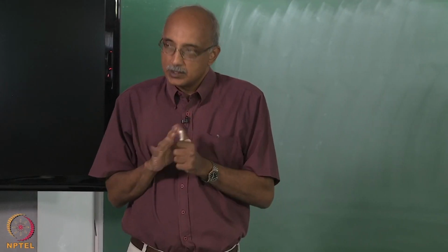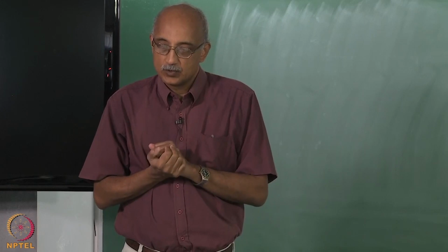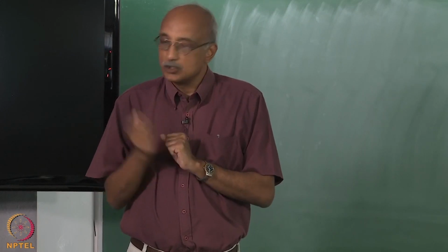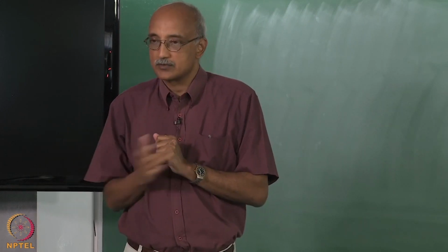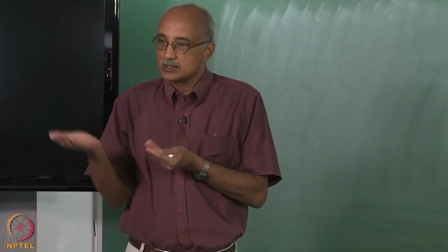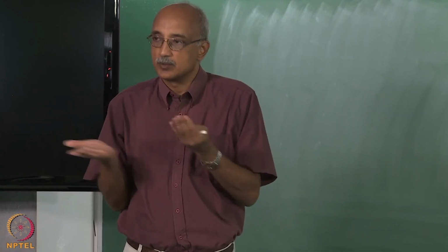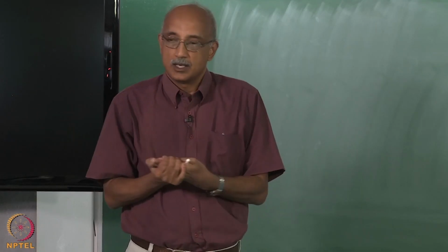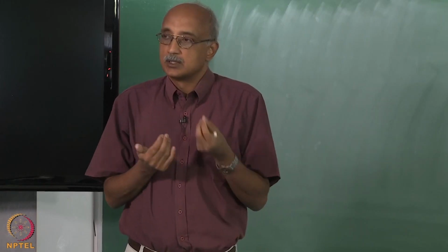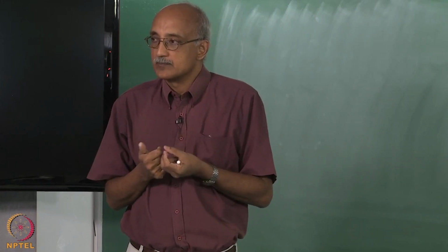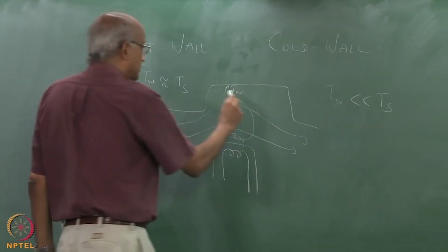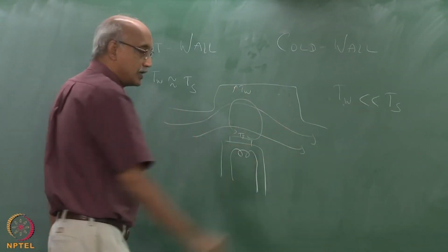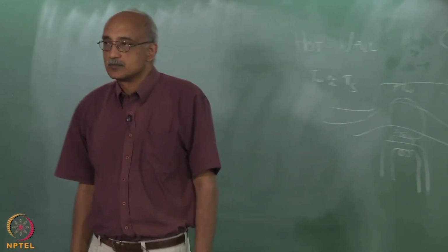The main reason you want a cold wall reactor is so that you make sure that the nucleation only happens in a heterogeneous fashion, because only the substrate is at a high enough temperature to actually promote deposition to happen, and you essentially preclude homogeneous nucleation from happening. Because in this configuration, all the rest of the reactor is at a much lower temperature.